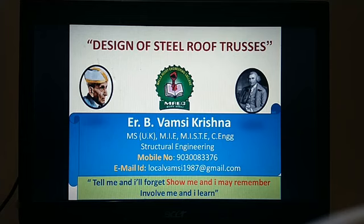Okay, so we'll start with the design of steel roof trusses. Basically, we go with these kinds of roof trusses whenever we require a column-free space. When the span is more, and we require a structure which should not have any columns in between, right? Column-free structures I can call them. Examples I can give are assembly halls, auditoriums, cinema theaters, airport hangars. These all come under roof trusses, where you will have a lot of free space without any column in between the structure, okay.